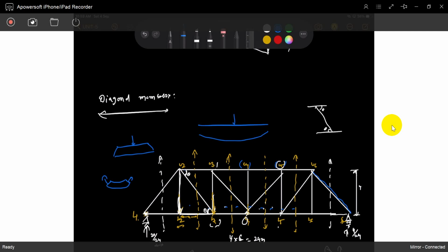So how to choose the point? Any point where two other forces meet, choose that point to take moments about. That is easy; we said it in the previous class. So any section, any member you can find out. If someone asks, no need to write down the ILDs for all 20 members. You have to find out one member and replicate with the others. No one asks to write down the 20 members.